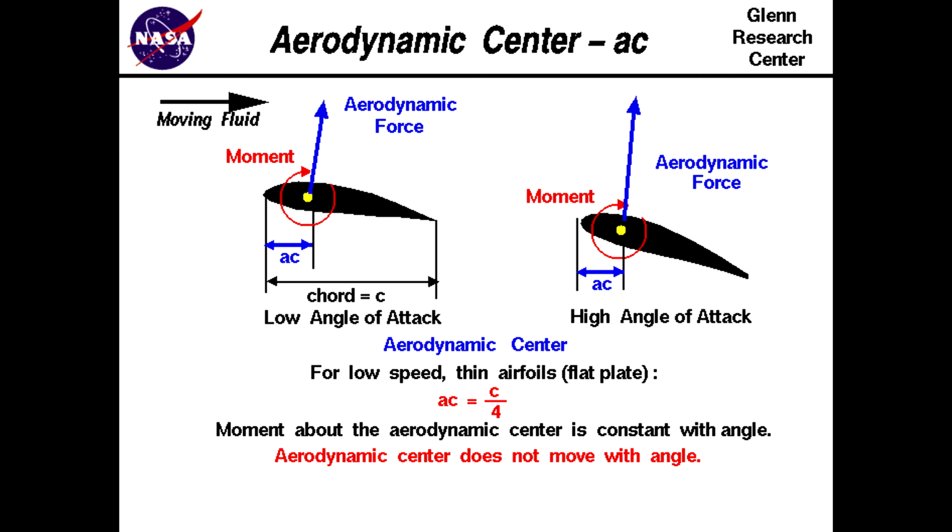It's a very common thing. There are different ways to simulate, right? You can put the origin of coordinates at the leading edge, at the trailing edge, or at the quarter chord, which I show how to do. And then you will receive the corresponding values of moment coefficients. But it's also always possible to calculate the moment coefficient for any point if you use the corresponding formula.